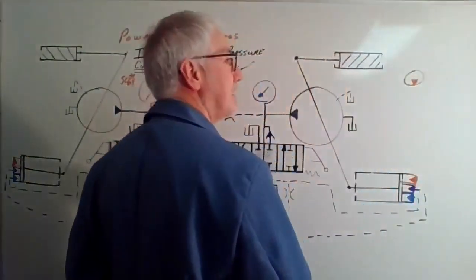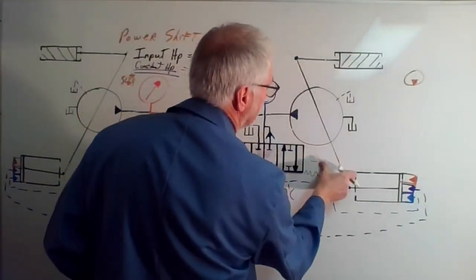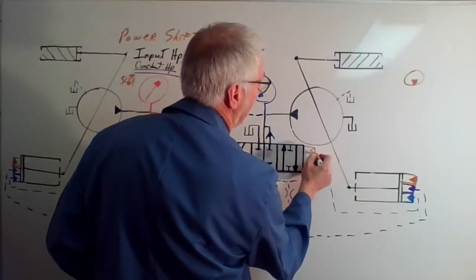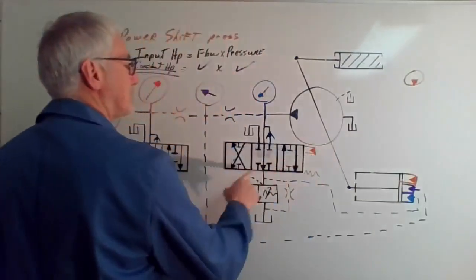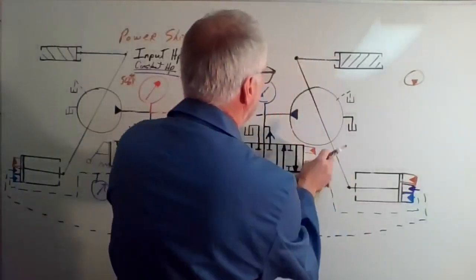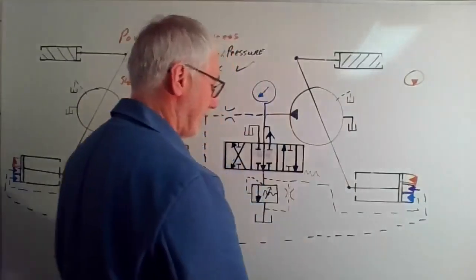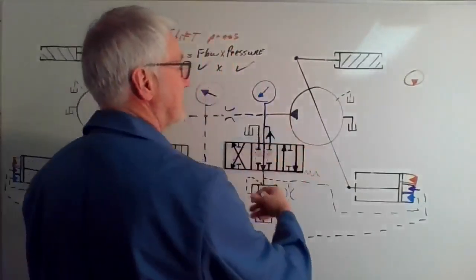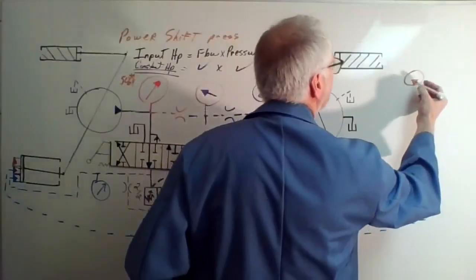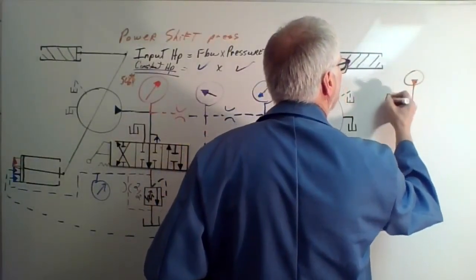Potentially we have another pump on there running some pilot controls, because for all practical purposes in today's world, we know that ultimately there's a hydraulic control running the main DCV. So even if I didn't have that, which would require pilot pressure, pilot operated DCVs, we know we've got a charge pump to protect these potentially.